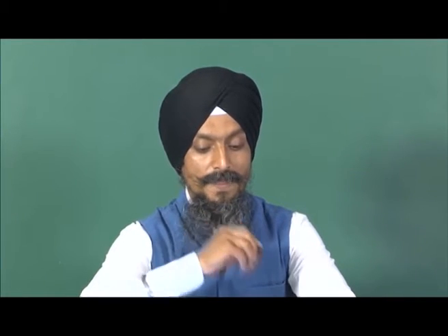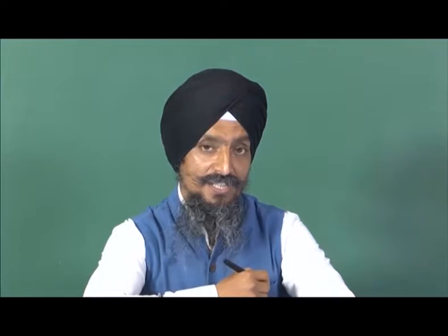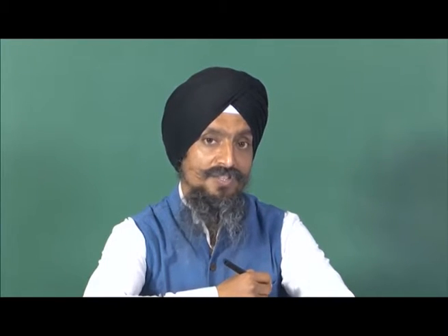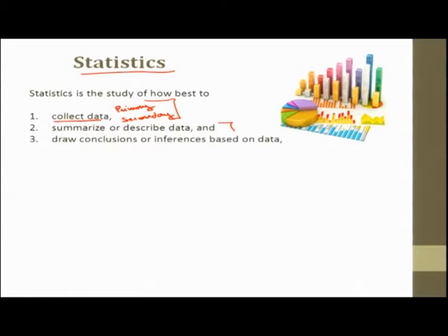When you purchase an instrument, say a vernier caliper, you know that the least count is 0.02 mm, and this is the secondary data, that is the value that is given. The data that you generate, the actual least count that you find out, is the primary data. Okay, so we can detail it further when we come to actual examples here.